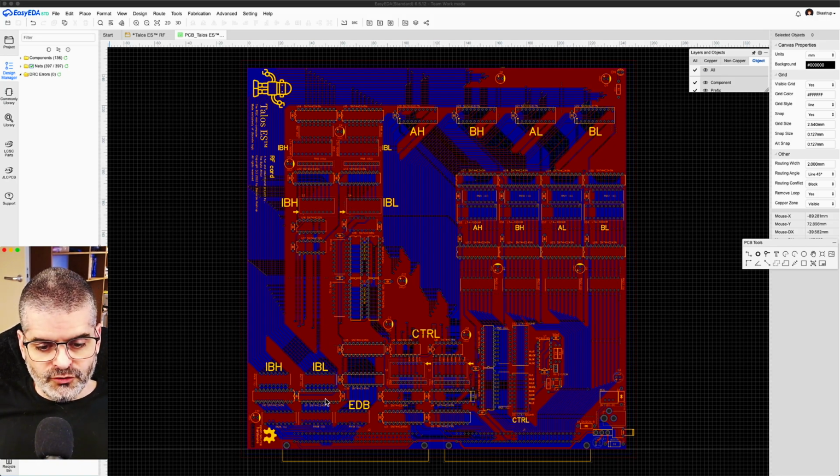Now, these 2 buffers connect the local bus to the internal bus of the other cards via the backplane, via these lines here of the backplane. And the buffers have resistor networks of 33 ohms on both sides. On this side to absorb the local reflections of these bus lines, because again, these bus lines, they have a lot of branches.